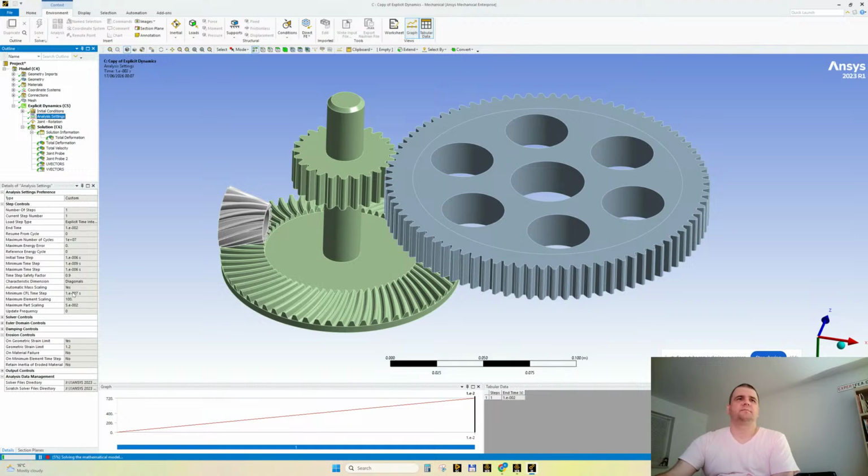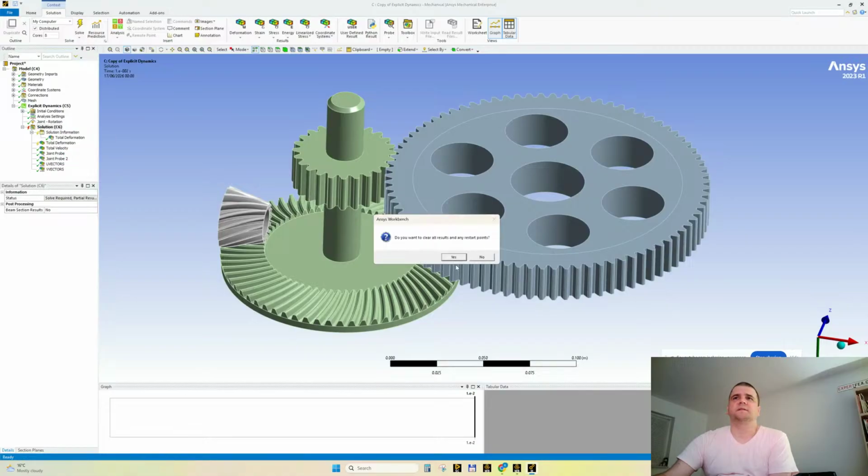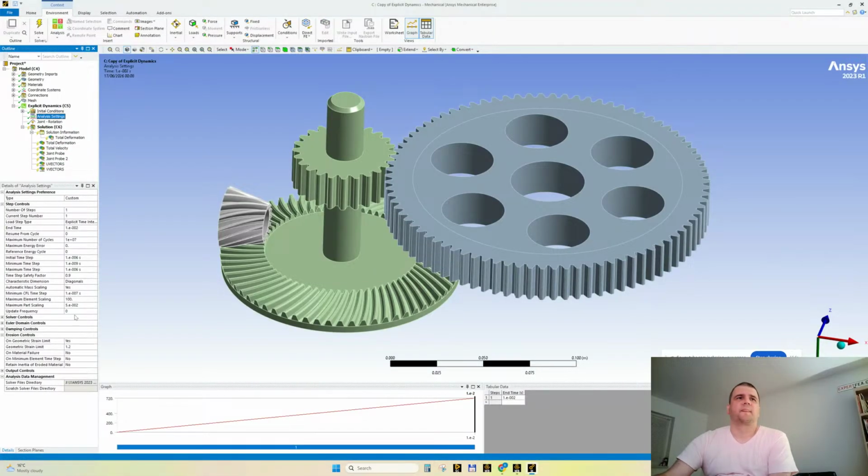And let's increase the Courant-Friedrichs-Lewy time step, CFL, named after the three mathematicians who proposed this option to decrease the solving time. All right, so let's delete a 0, 1e-6. And if I am correct, with maximum part scaling, the default value will not work. Look here.